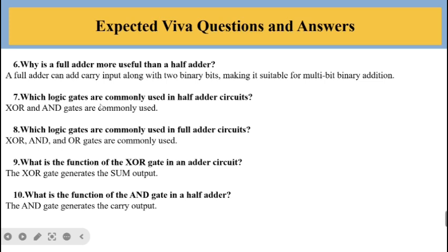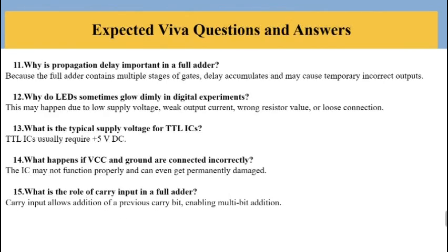Which logic gates are commonly used in a half adder circuit? XOR and AND gates. Which logic gates are commonly used in full adder circuits? XOR and OR gates. What is the function of the XOR gate in an adder circuit? The XOR gate generates the sum output. What is the function of the AND gate in a half adder? The AND gate generates the carry output.